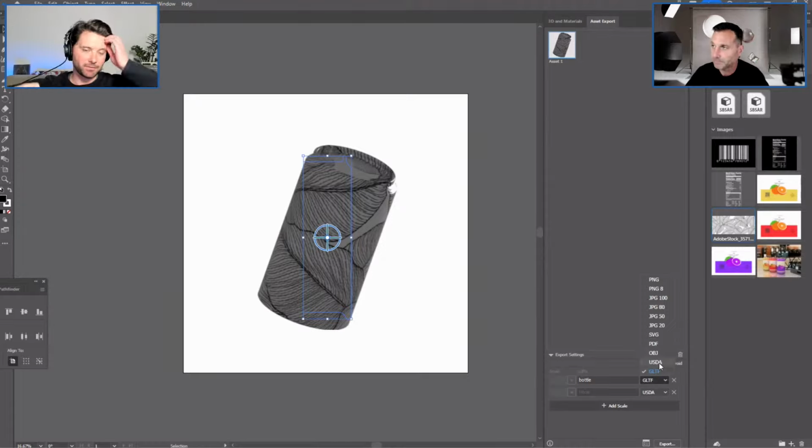So just jumping in there, that file format will bring in the 3D object, but it'll also understand that it's bringing in a material, so it's saved within that type of file. So when you're going into another 3D program, those sliders and options and all that sort of stuff will be part of it? Some of them, yeah. Most of it, it'll just bake all that down. So it'll take the material that you've assigned to it. It won't expose those parameters once you've exported that out. So you would do all your tweaking in here and then export it out.